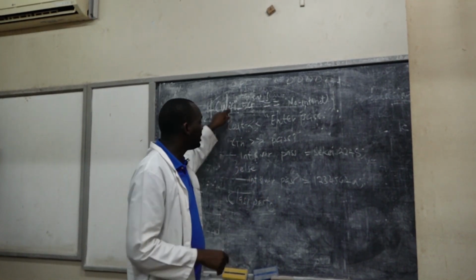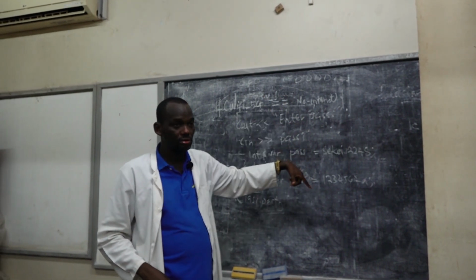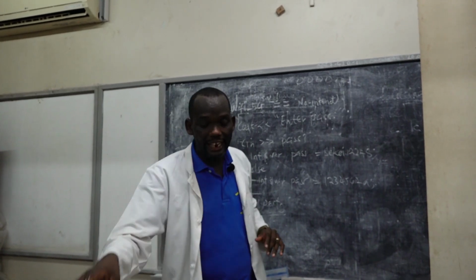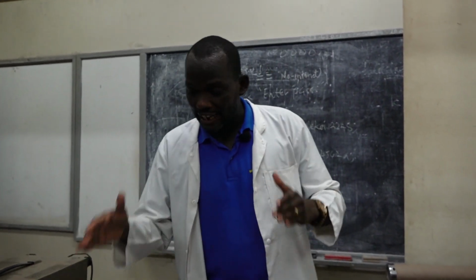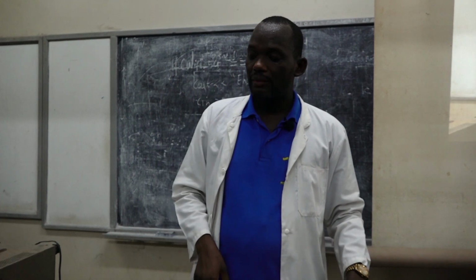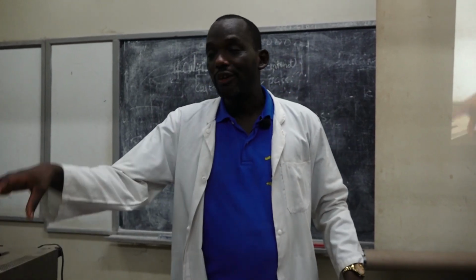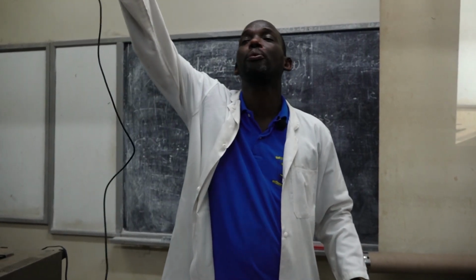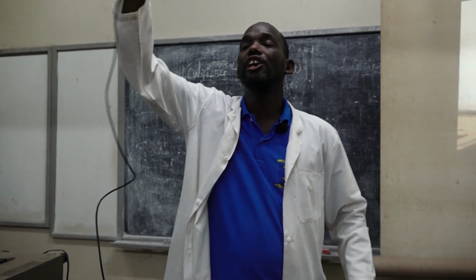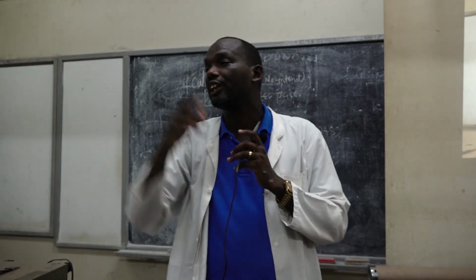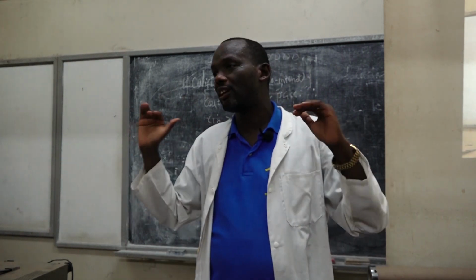I told you that the first waveform is sinusoidal, right? Which promotes the main AC. That's what you have to display. I told you, according to the manufacturer's setup, that we cannot connect this digital oscilloscope with the AC mains by using this BNC probe. You cannot take this probe and connect it directly to power or to the cable. Why? You are going to destroy the probe, and you are also going to destroy the digital oscilloscope. That's the simple point that I was teaching.